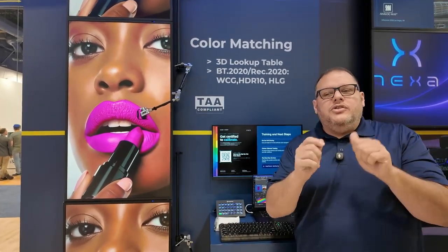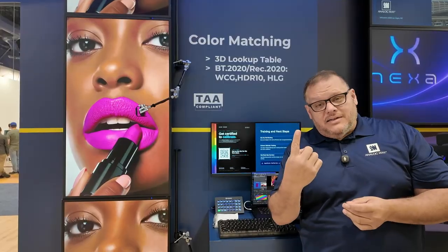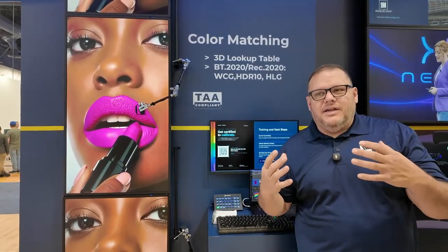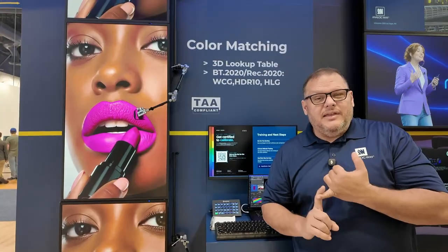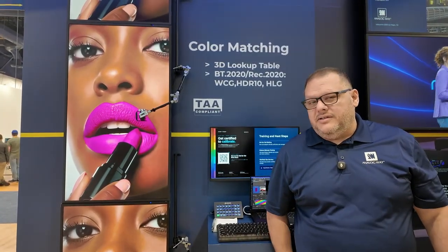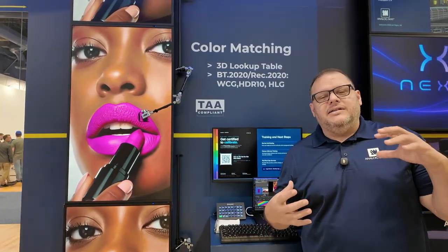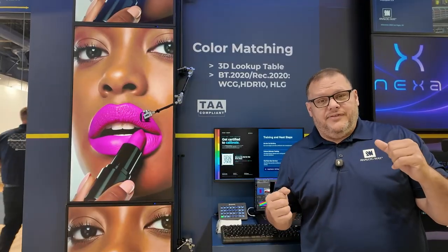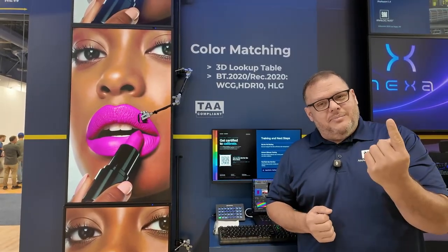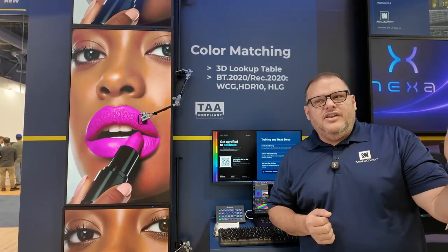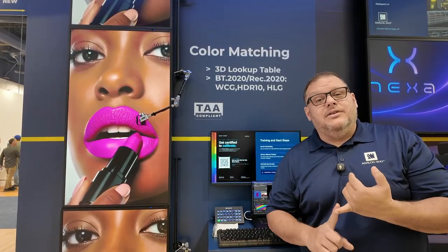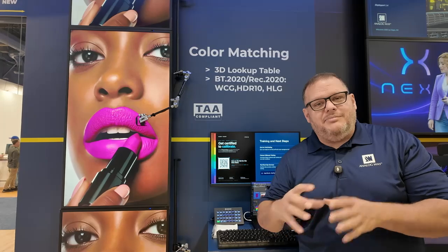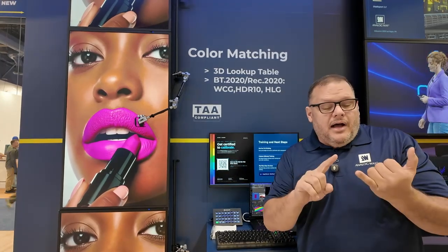One other thing is, usually to have one LUT box, there's a couple of LUT boxes out there that are really good, but are about $3,000 a piece. Now this, with two LUTs on the input, two LUTs on the output, a fully loaded RS6 has 104 LUT paths. Usually if I had to buy one of those LUT boxes, about $3,000. Now one thing is, you have to break down the connection to SDI only on that LUT box, and it goes down to 422, and it goes down to 8-bit. 8-bit means banding. Here, we have zero latency, it's built into the processor.